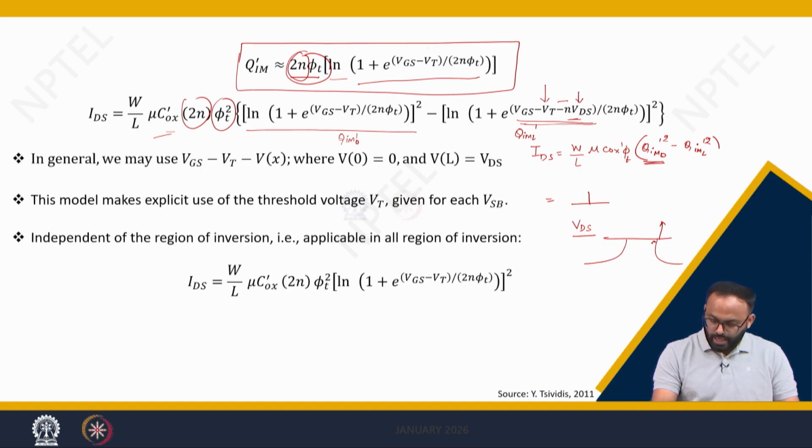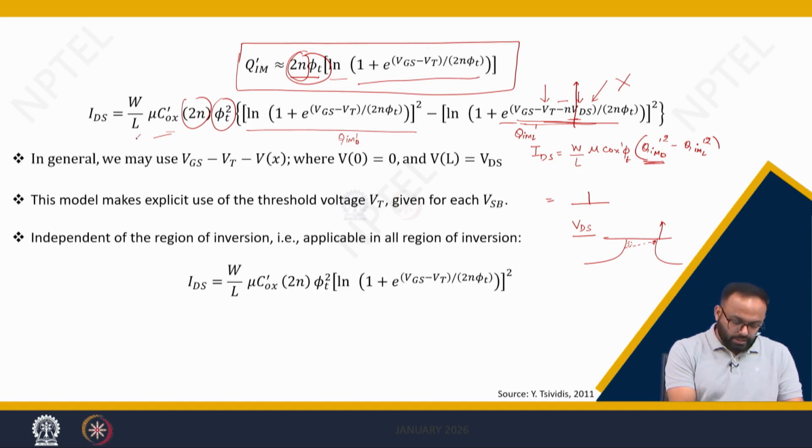It means in the MOSFET you are increasing Vds, so at this edge you are going to weak inversion or depletion. However, this is in moderate inversion. So ultimately you can say my device is in moderate inversion, but this factor will disappear, because if you increase Vds, this factor will disappear, correct. So you can simply rewrite a single form of equation which holds good everywhere.